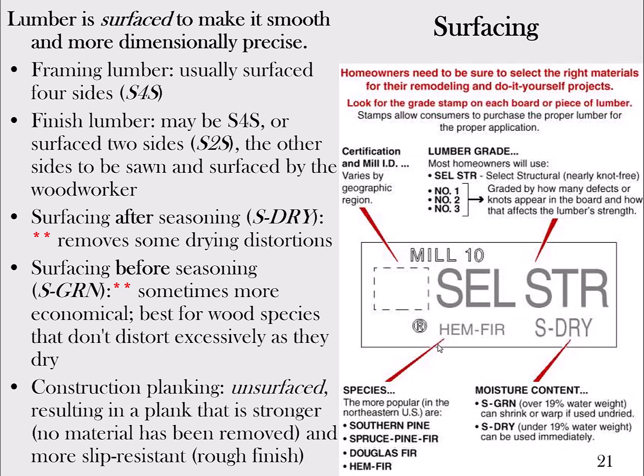When you go measure your 2x4, you'll discover you got ripped off. It's not 2 inches by 4 inches. It's 1.5 inches by 3.5 inches. So it's a 1/2 inch less in both dimensions. But it started off being rough cut, maybe pretty close to a 2 inch by 4 inch board, and then it shrunk through the seasoning process, and then they resurfaced it.